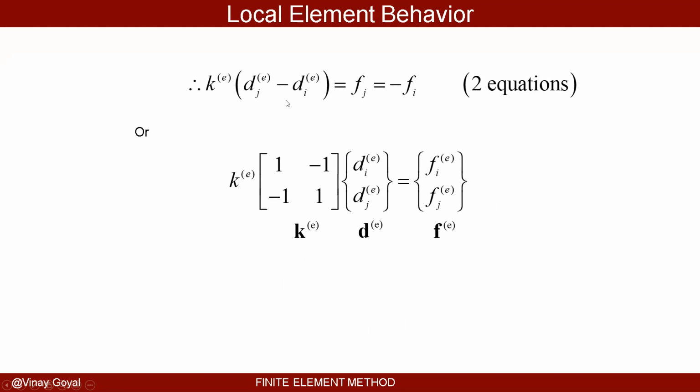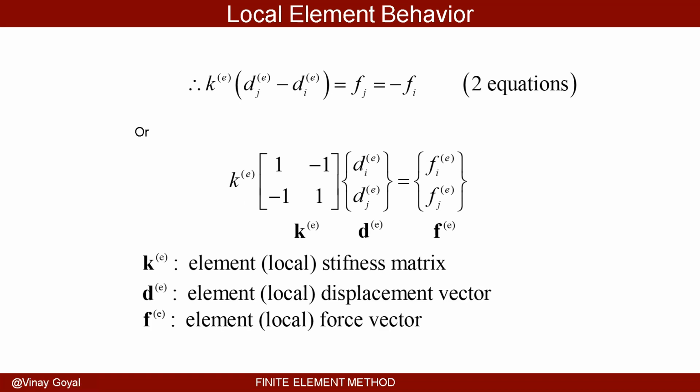And so every single element is going to have this representation. The element stiffness matrix, listen to my words, the local element stiffness matrix, local, we're deriving it for a single element, the master element. Every other element is going to try to follow that, and we're going to try to derive it as generic as we can. This column vector is D, this column vector is F. Again, K is the element local stiffness matrix, D is a local displacement vector, and F is a local force vector.